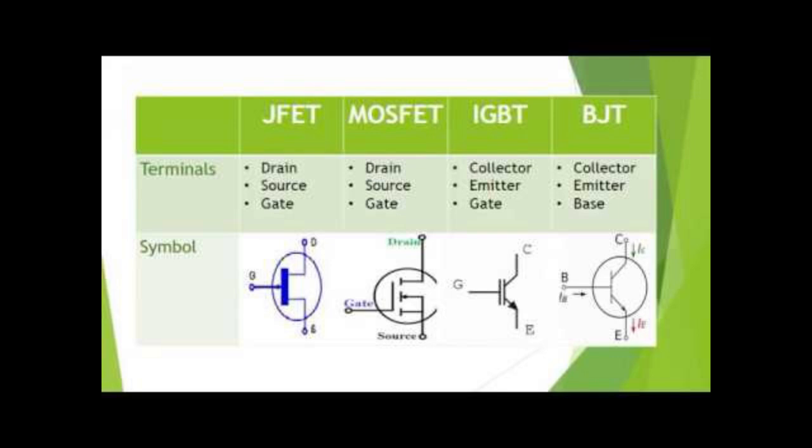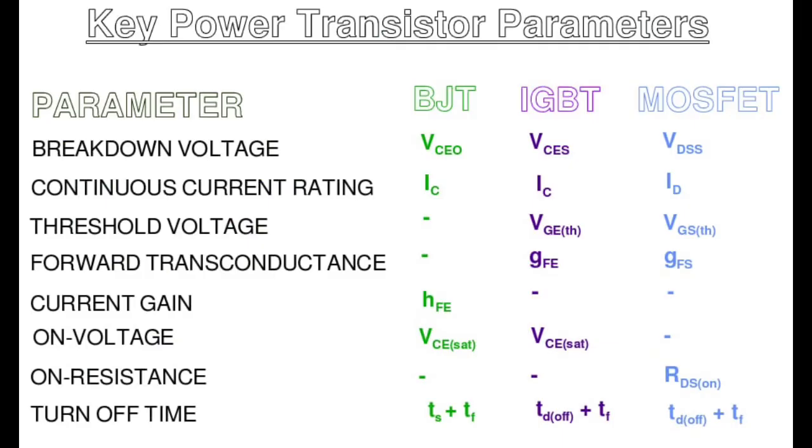Thirdly, silicon is the dominant material for BJTs due to its thermal stability, electrical properties, and cost effectiveness compared to germanium. Understanding BJTs is crucial for circuit design because, firstly, terminals. Knowing the roles of the base, collector, and emitter allows designers to properly bias the transistor for amplification or switching. Incorrect biasing can lead to malfunction or damage.